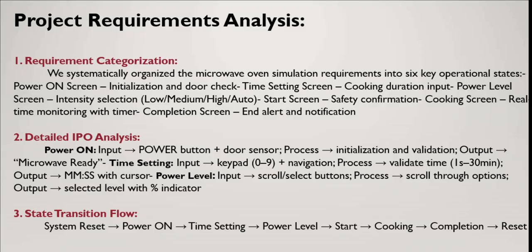We used MPLAB X IDE for writing, compiling, debugging, and simulating embedded C programs. The XC8 compiler converts the C code into machine-level instructions that the microcontroller can understand. Simulation helped us identify errors early, reducing hardware damage and saving development time.